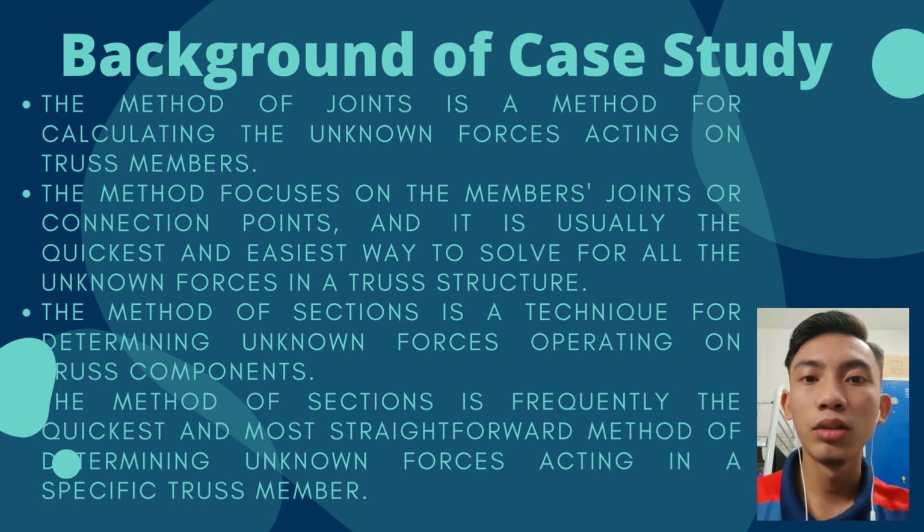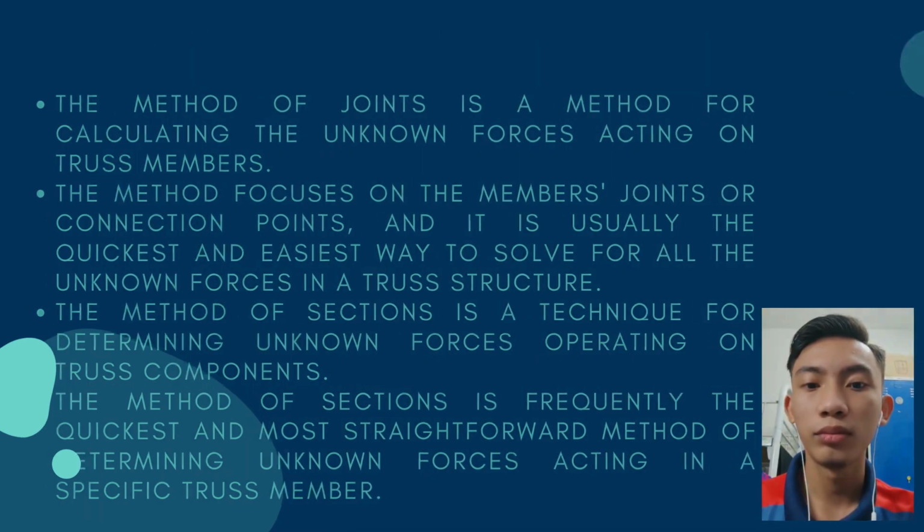Once you have made a free body diagram, write out the equilibrium equations. Because there are extended bodies, you will need to write down force and moment equations. You will have three possible equations for each section, two force equations and one moment equation, which are sum of forces equal to 0 and sum of moments equal to 0.